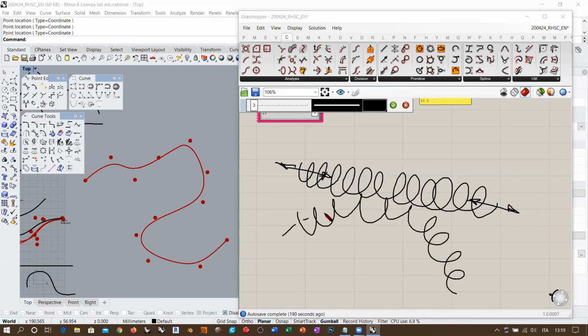Now, if you consider the bending problem inside the elastic simulation, you have a very, very complex differential problem, right? So Kangaroo is based on a schematic approximation of the spring, which is called the ideal spring, that cannot bend. It can only stretch along the longitudinal axis. And therefore, Kangaroo can only work with linear springs, so straight lines.